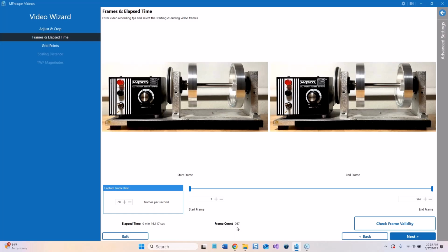And the algorithm is going to extract a time waveform from each frame of the video. So I'm going to end up with a data block full of sampled time data, just the same as if I'm acquiring data from an analog signal from accelerometers, multi-accelerometers or a single accelerometer. Each channel in an FFT analyzer will sample the data exactly the same as what we're doing here with a video.